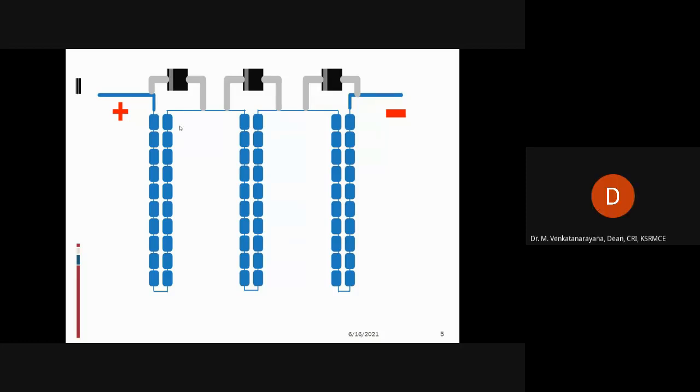Okay. So how are solar PV panels made? Solar cells are connected in series and grouped, then it makes a solar PV panel. Each box will be considered as a solar PV cell. Each group of cells connected together makes a solar PV panel. Under normal conditions, at the top of the screen there is a diode. It is called a series diode, which is connected in reverse bias mode. I will let you know later why it is in reverse bias mode.